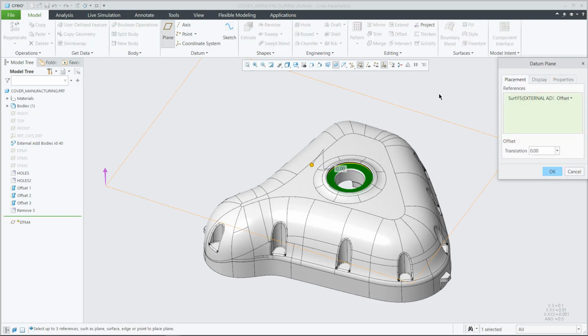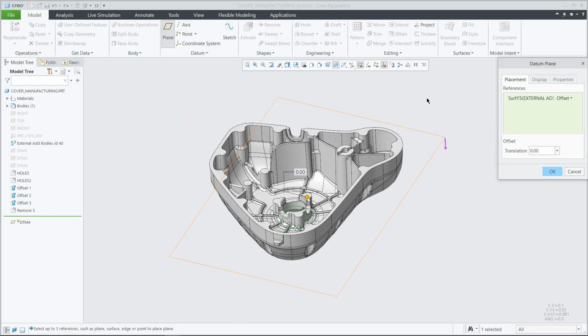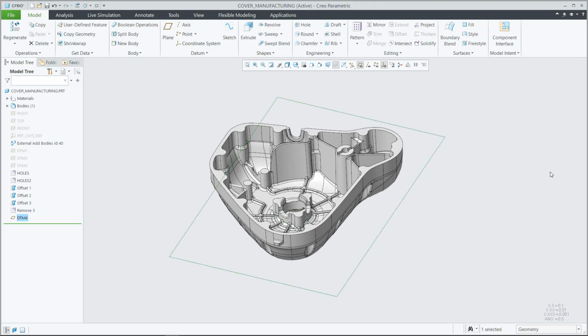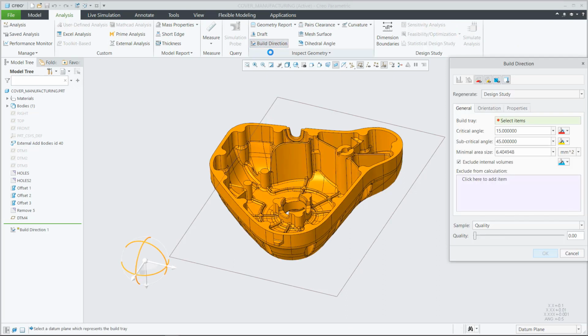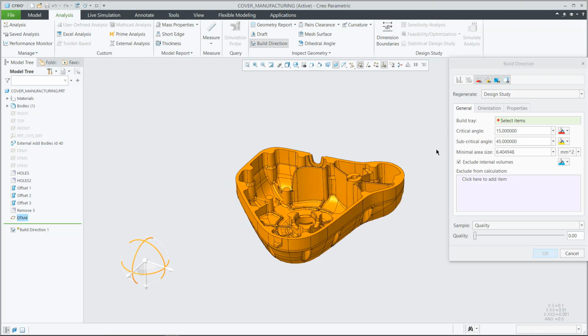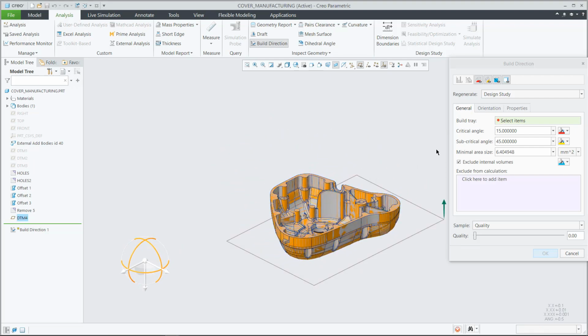So the first thing I'm going to do is build a plane here at the bottom, because I'm going to use that to determine the optimal build direction. This is an issue of if I just put that flat into my printer, I'm going to have support structures over almost the whole interior here, assuming it's facing down. Because if it's anything over a certain angle, I have to be able to put support structures inside the 3D printing process, and those have to then be removed later.